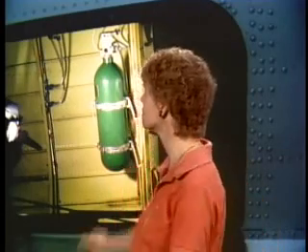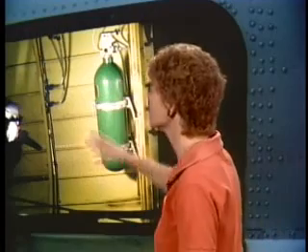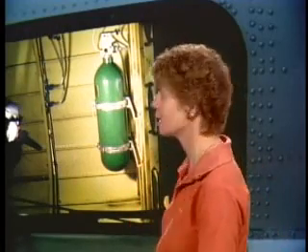Now, if you suspect that the aircraft oxygen system has a leak in it, the way you test the lines and fittings is by bubble testing with a testing soap solution that is made specifically for that purpose. So you can bubble test it with a soap solution. What you don't want to do is run around with matches trying to see if you get any flame off, because boy, you could sure get quite an explosion if you really do have a leak in the oxygen system.